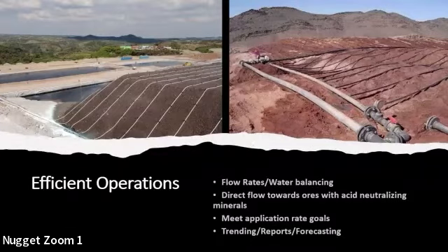So here are some readouts of typical CPTU readings. As you can see, it was very straightforward, and there are some gaps here, from 40 meter depth to 20 meter depth. There were some points that couldn't be addressed in more detail, which were later evaluated with the samples that were coming out of those.